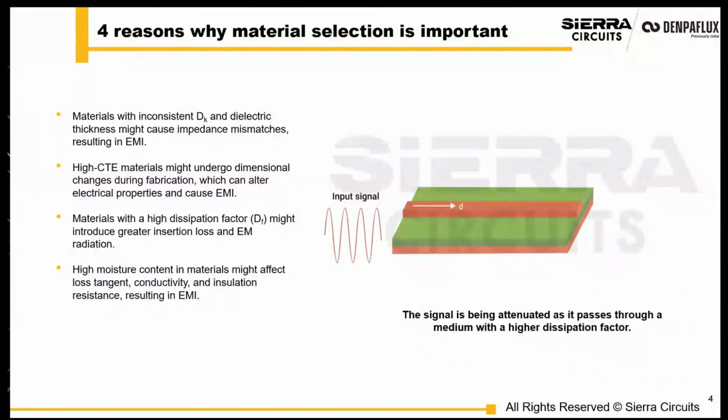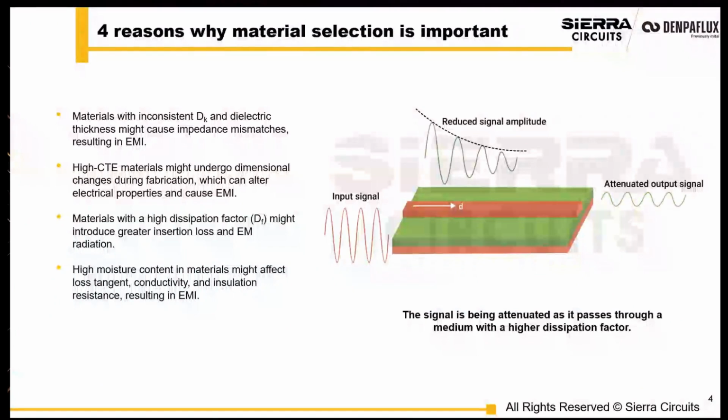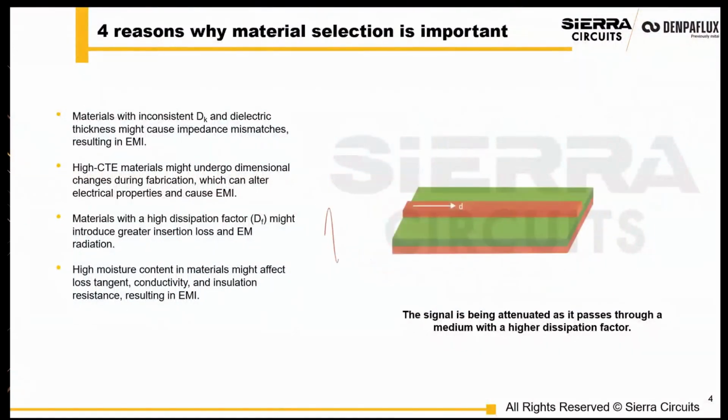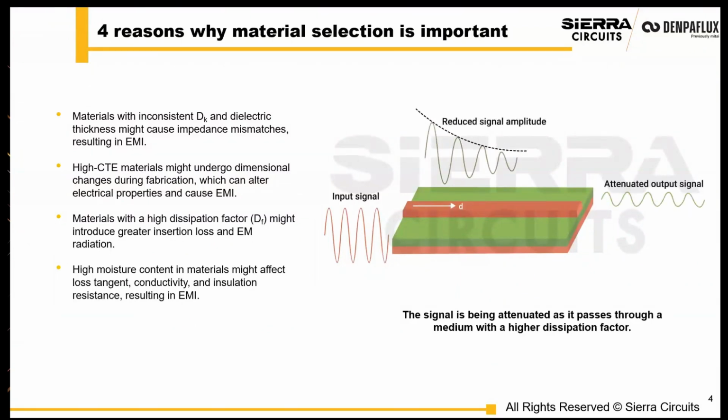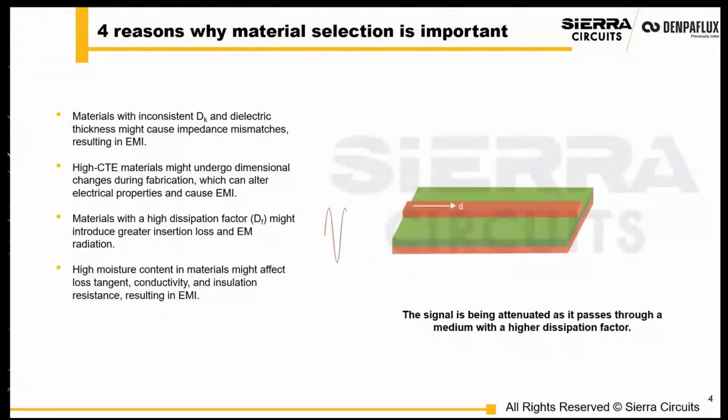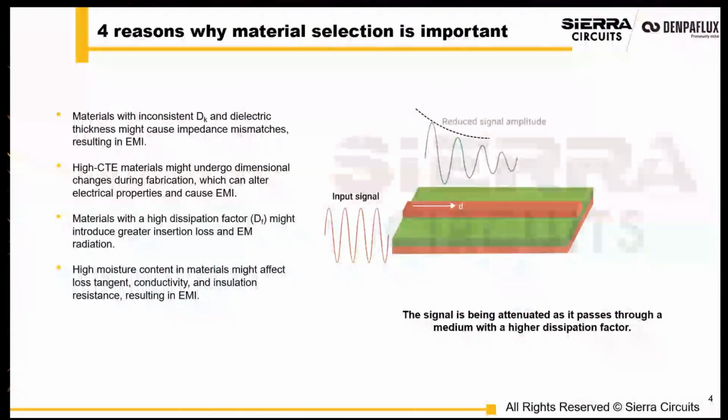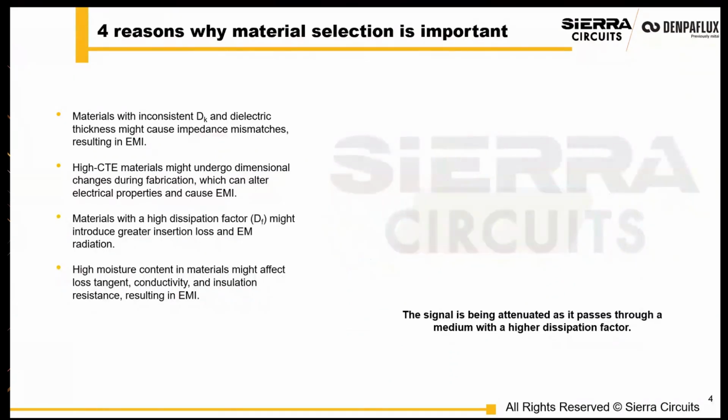So from a fabricator standpoint, prior to shipping, the PCB manufacturer should bake the boards to make sure there's no moisture within the boards, especially important for rigid-flex. And you might want to consider packaging in a vacuum type of situation and using a little bit more expensive packaging to make sure that there's no moisture issue over time.